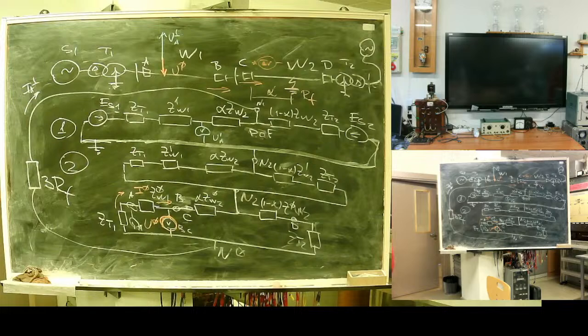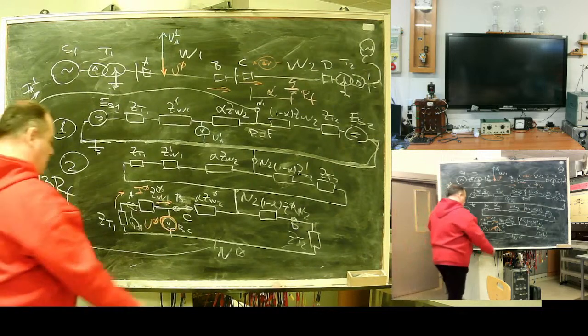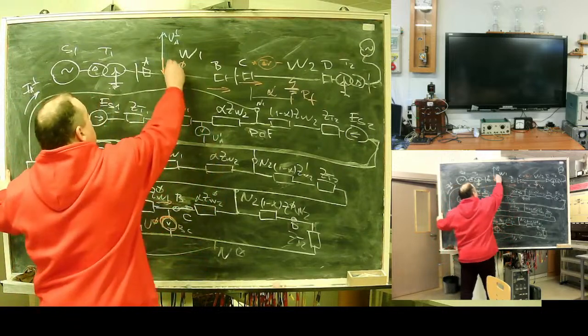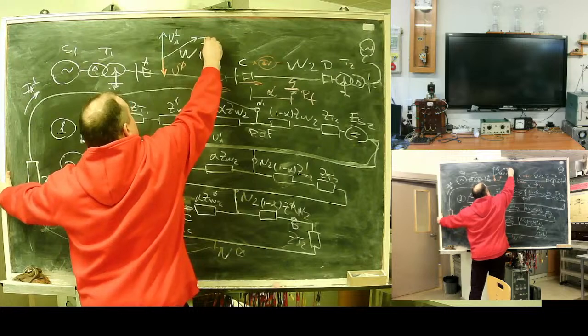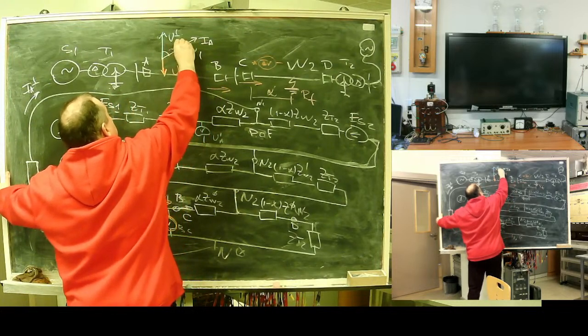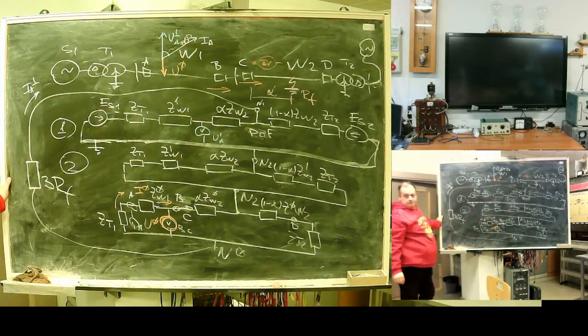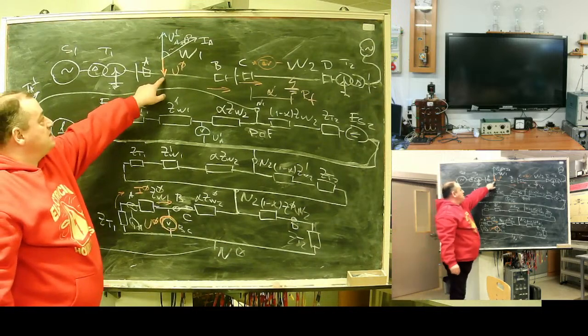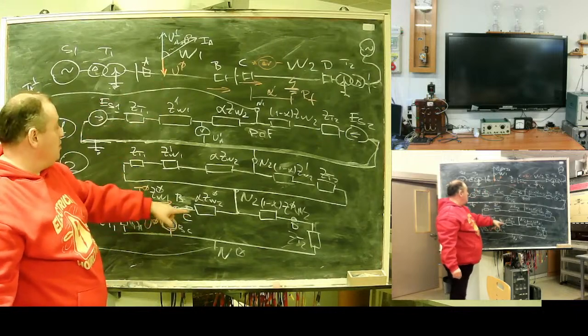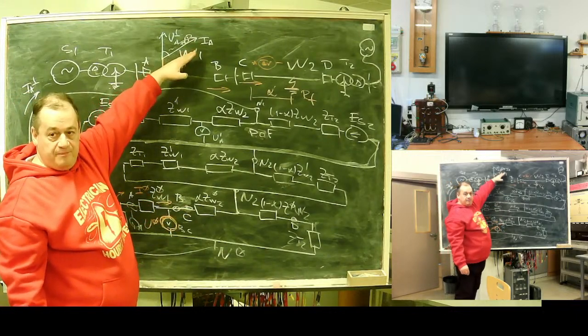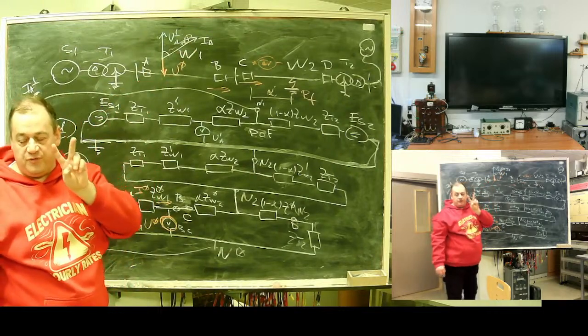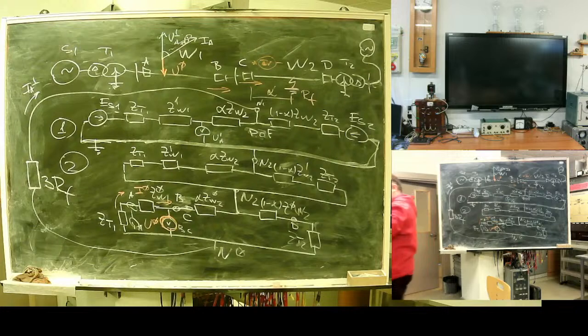Current, where will the current be? For typical network, current is approximately 70 degrees and lagging. Now, careful. Here is your zero sequence voltage. Current goes the same way. There are two types of relays. The key moment is direction.